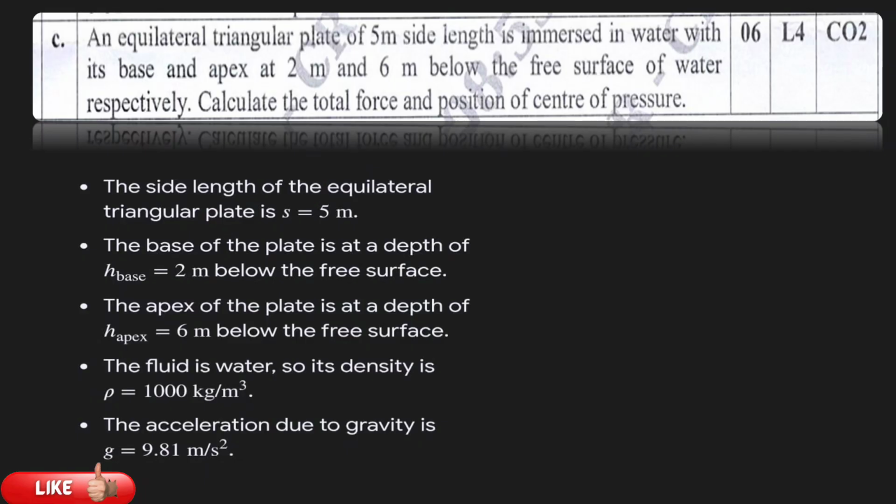An equilateral triangular plate of base 5 meter is immersed in water, base at 2 meter and apex at 6 meter from the free surface of water. Calculate the total force and position of center of pressure.